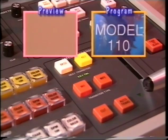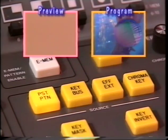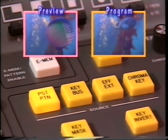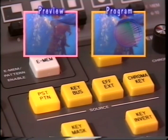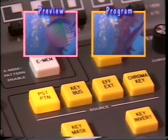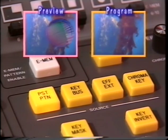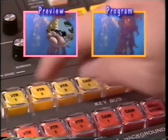The second type of key available in the Model 110 effects keyer is Preset Pattern. Preset Pattern enables you to perform a transition to a split screen effect. The procedure for setting up this effect and taking it to air is the same as that for a luminance key, except that Preset Pattern is selected as the source and a key bus crosspoint is selected as the fill.